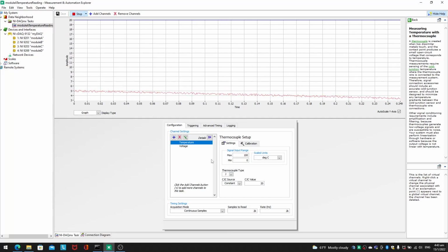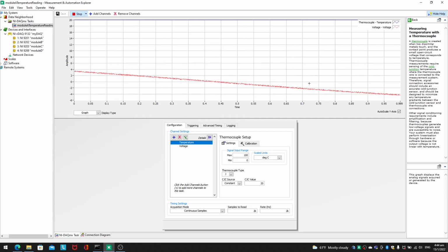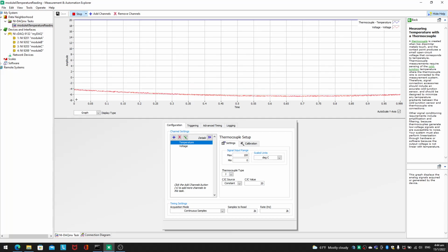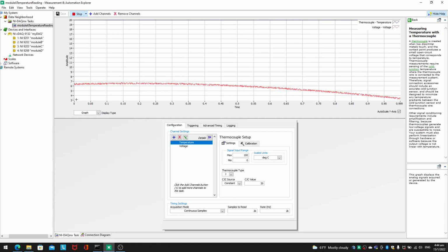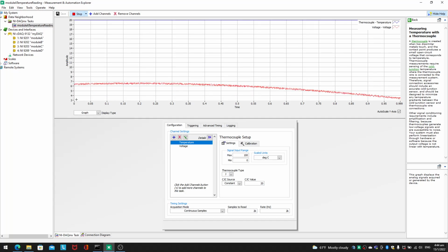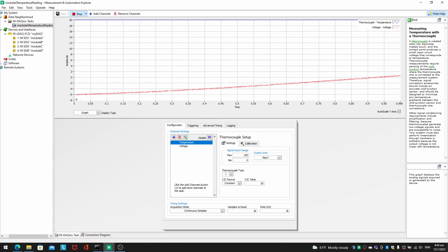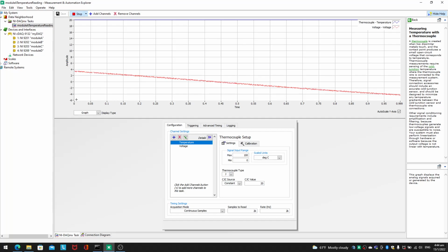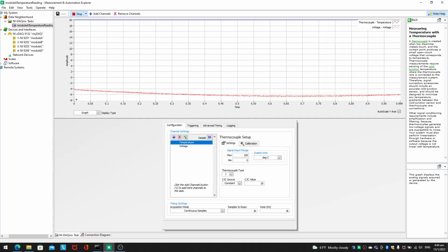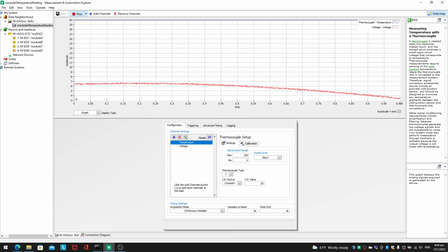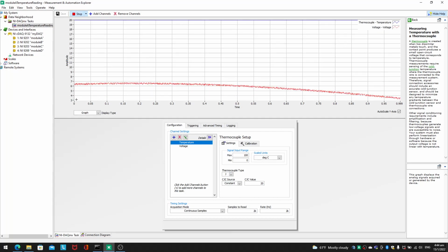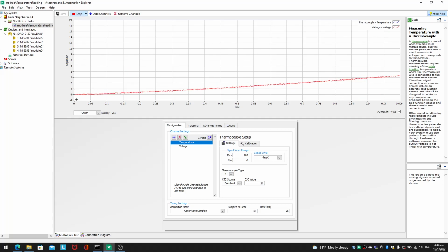If you change this to 2000 samples to read, you should be able to see one full sine, or at least a bigger version of a full sine waveform, because you're taking 1 second at a time. So every second this voltage sine wave is changing. So that's all. I showed you how to create virtual instruments, so to speak, or at least a virtual DAQ with virtual data. With that, you are able to play around with either LabVIEW or Python code to connect to these virtual DAQ devices and do stuff with it.